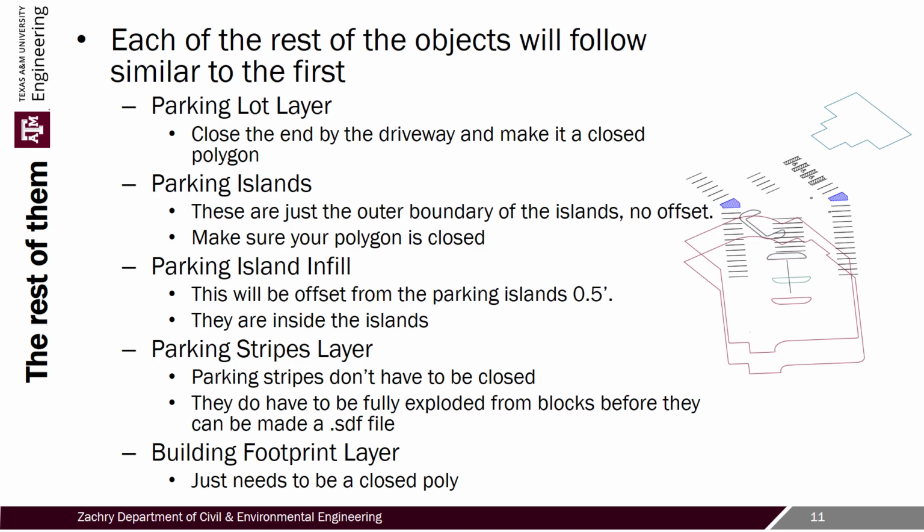And so we're going to explode them out until they're just back to their raw lines, and then we'll bring those up. And then the building footprint's just a closed polygon of the building footprint. So those are the ones that we're going to bring in.